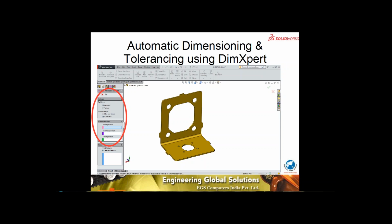The automatic dimensioning and tolerancing using DimXpert follows the ASME Y14.41-2003 standard of the American Society of Mechanical Engineers in terms of the digital product definition. You can use plus or minus tolerancing, or you can use geometric dimensioning and tolerancing. If you look at the circled area, you would be able to see the different types of options provided inside SolidWorks for you to develop a complete and correct representation of drawings, either using plus or minus or using geometric dimensioning and tolerancing.